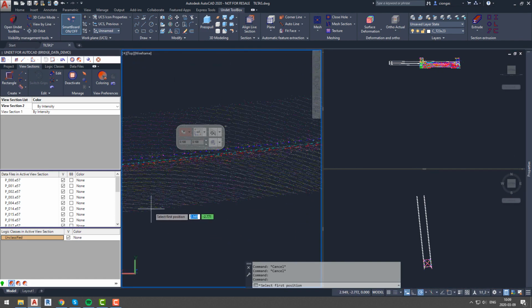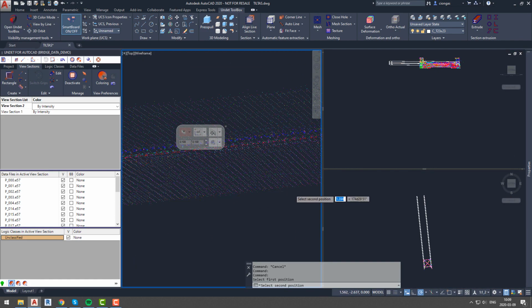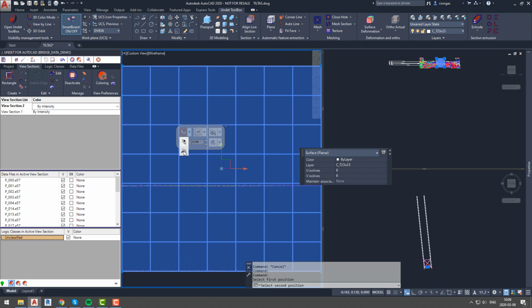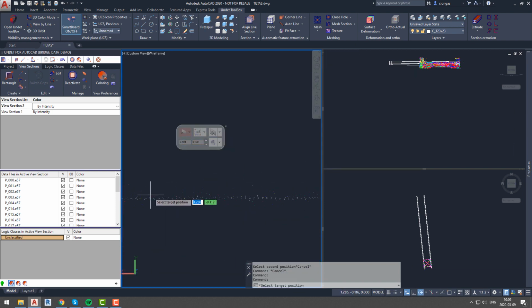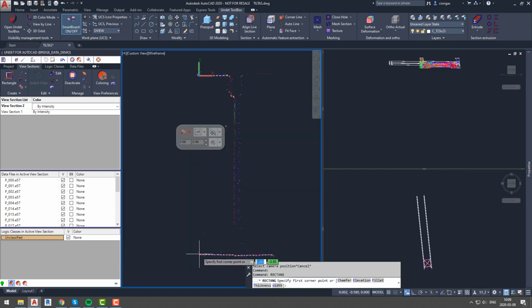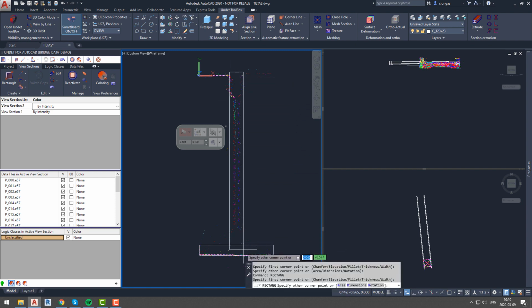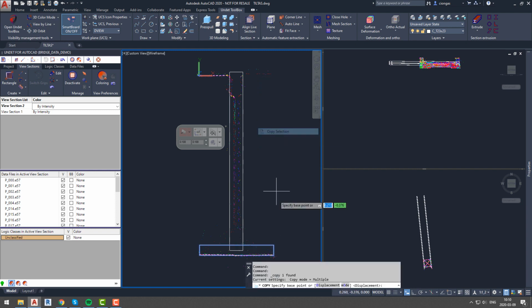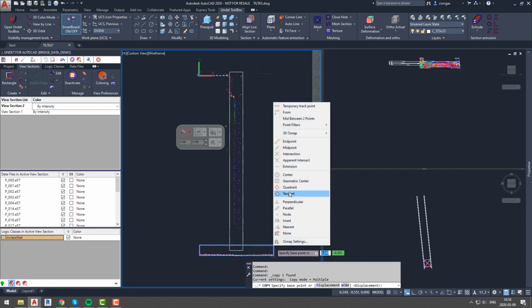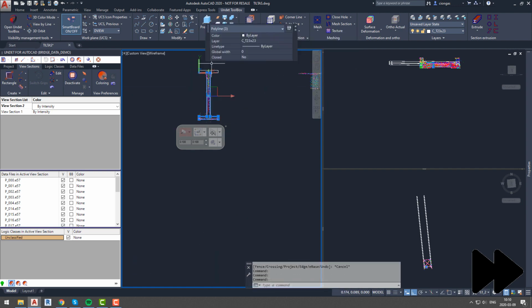So workflow will be the same for every element that you want to model using Smart Board tool. First we will use cross-section tool to specify element that we are interested in, and after that we will create profile section, so that we will be able to follow outline of element in correct plane and UCS. This time we will use another option to model our beam. This time we will draw rectangles or poly lines and join them into single figure which we will extrude later.